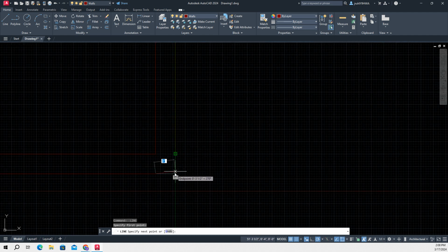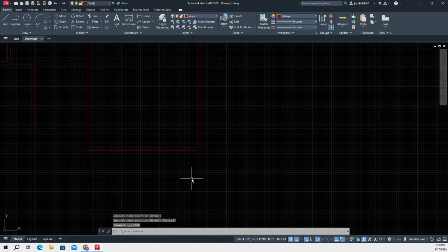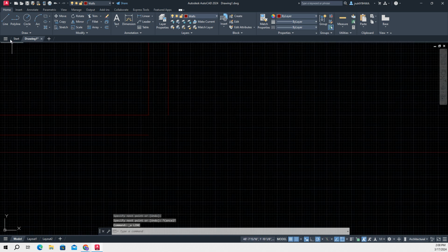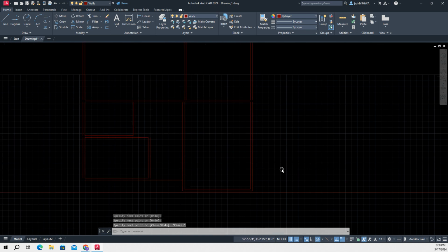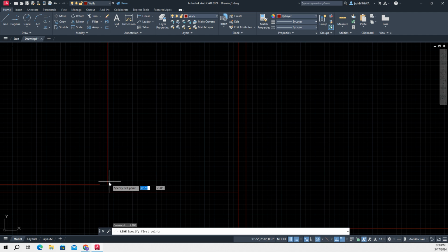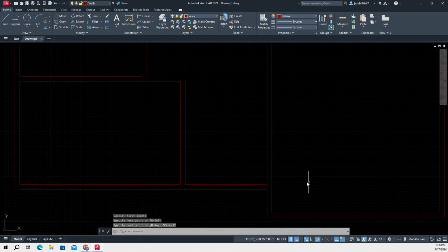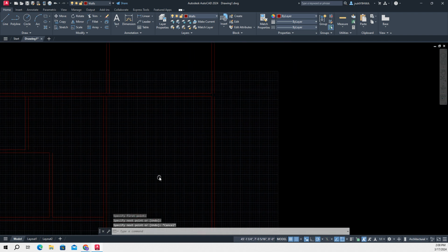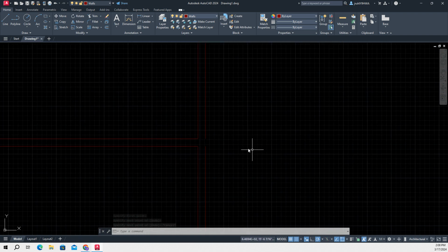All right, so using my polar tracking stuff and everything else like that, I can take it down from this point. I could see where it's even, and then I can go up in my on step. If it's looking for endpoints, it'll match up that way. And then I'm gonna go back and turn polar on. That green line means it's 90 degrees, so I can finish some of these walls where I need to.